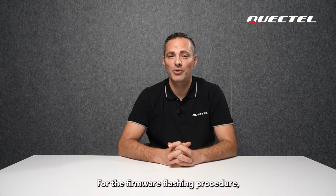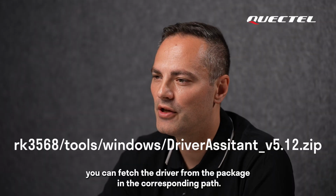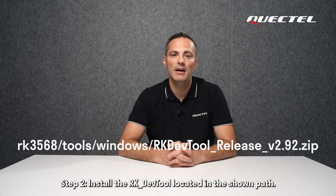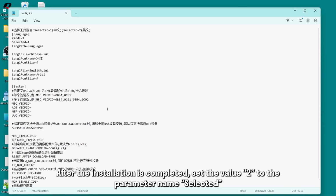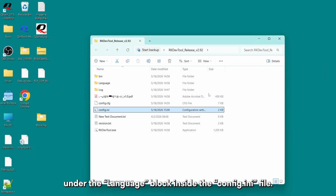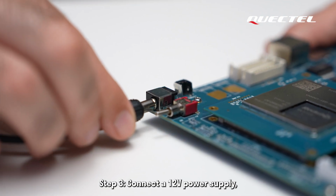For the firmware flashing procedure, follow the steps below. Step 1. Make sure the USB driver is installed. You can fetch the driver from the package in the corresponding path. Step 2. Install the RK-dev-tool located in the shown path. After the installation is completed, set the value tool to the parameter name selected under the language block inside the config.ini file. Step 3. Connect a 12-volt power supply.